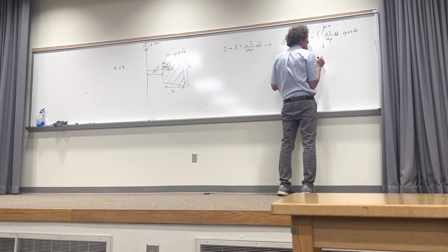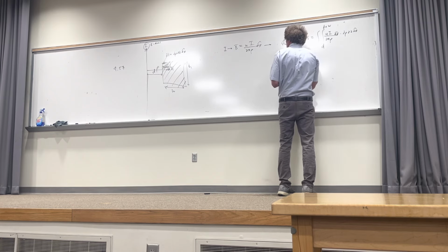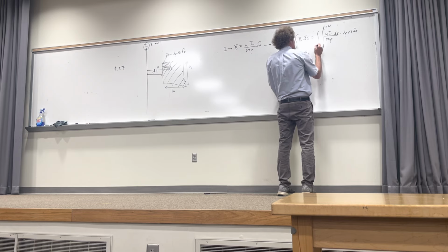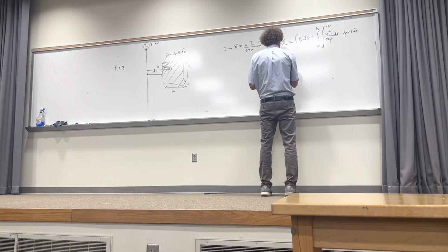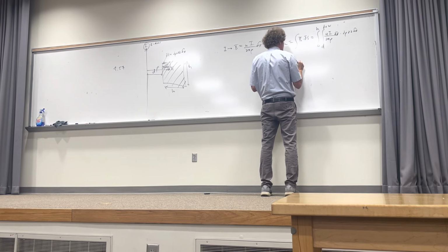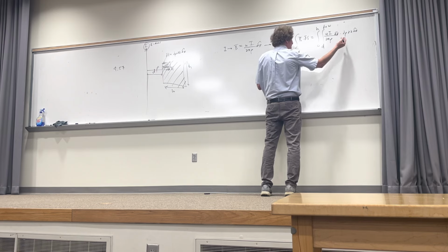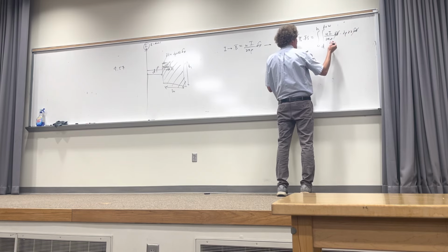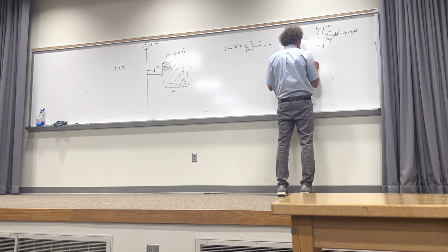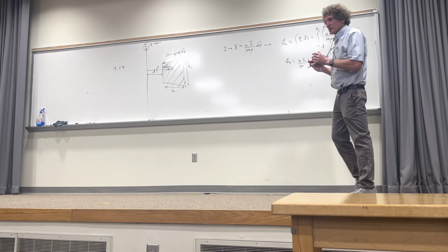What about Z? Take a look. 0 to H. Here H isn't 1 necessarily. That's the integral, and you can see that the magnetic flux therefore is mu I over 2 pi. And then we integrate dz from 0 to h. The A phis dot out to 1. We simply get h, and we integrate 1 over rho d rho, we get natural log here of d plus w over w. And that is the magnetic flux, right?